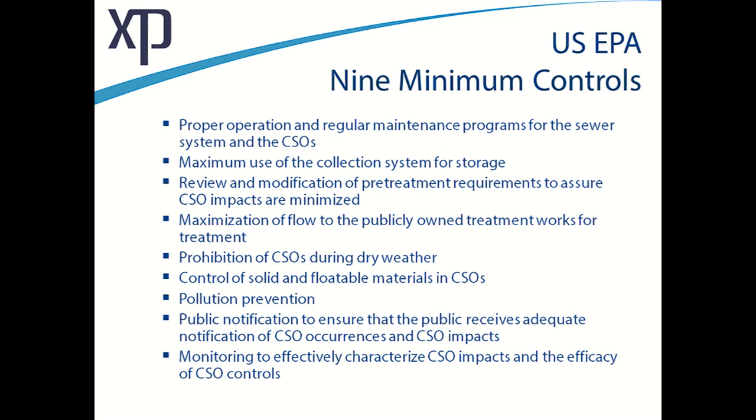They are prohibited during dry weather. So if there's no rain, there better not be any combined sewer overflows, and if there are, you have to explain what happened and why. And that goes back to the first one of maintenance, right? If it's well maintained, everything should be working correctly.